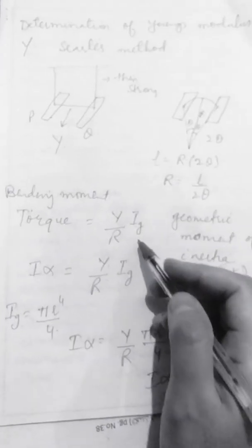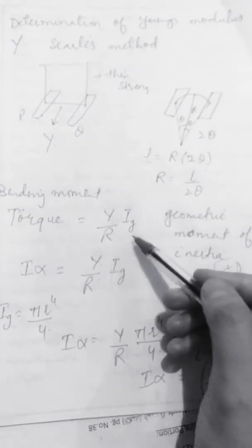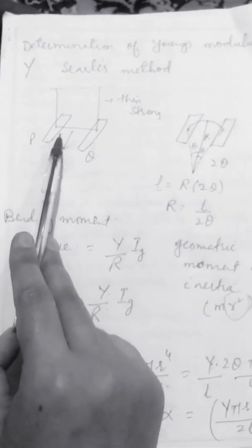So that is how we have used this formula directly over here. I tried to show you that because I thought that many of you might not be aware of this formula. So today we have discussed determination of Young's modulus using Searles method, in which we have connected two metallic rectangular bars with a thin wire, the wire whose Young's modulus we intend to calculate. These metallic bars are suspended by two thin and strong wires. Then we bend it like this, and then we do these kinds of calculations, as simple as that. I'm turning the pages again so that you can recapitulate. So this is the required formula, and then on the next page I have shown you how we used this kind of formula, right? So that's all.